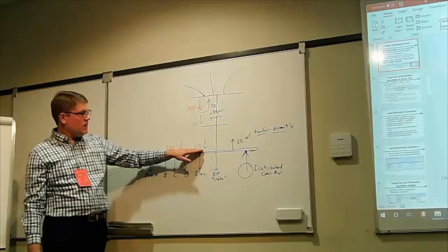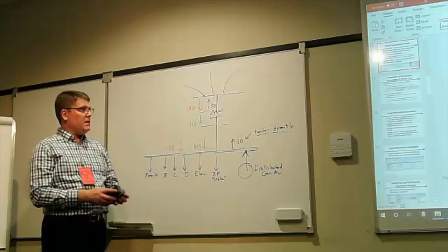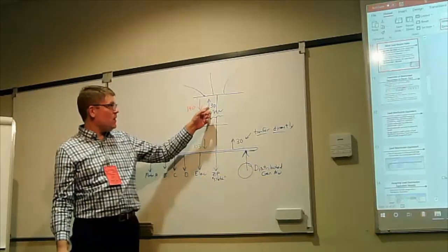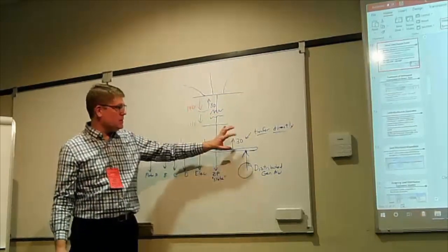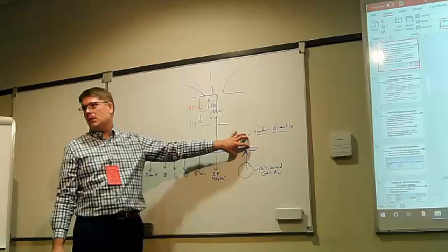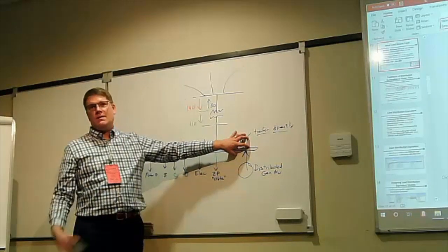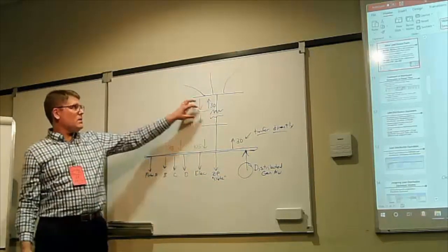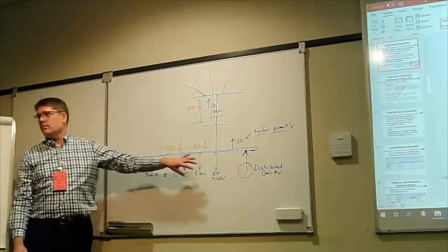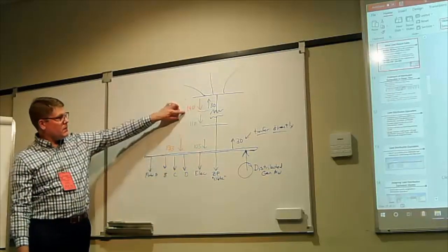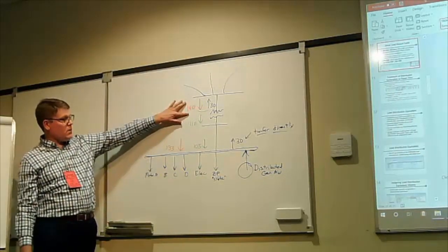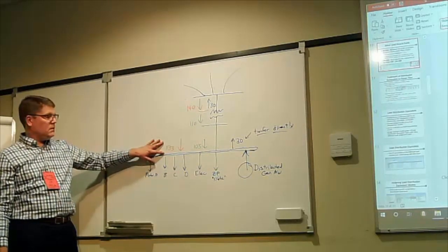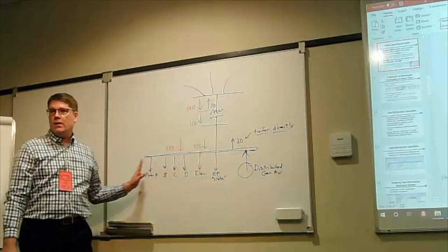That's how these feeders are set up. You get down here, and by definition, because I decided it would be that way, we assume that all the distributed gen just translates directly down there and does not contribute to the losses. Basically because it's easier to code. And all of the losses are assigned to the loads. So we get 103, so we started with 140 megawatts of load. We're down at the end of the feeder, we have 133. And then those get split up amongst all of these pieces.